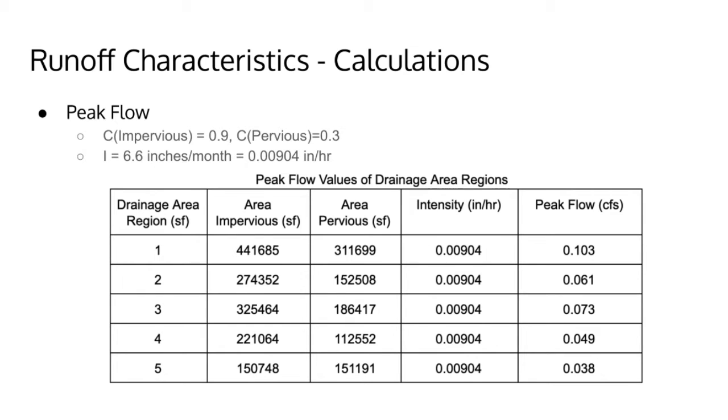In order to figure out the rainfall intensity, we had to look back at the information from our previous rainfall data. As a result, we noticed that rain peaks in Oregon during the winter, based on the average of the winter months. For accounting for capturing larger storms, we get an intensity of 6.6 inches per month.